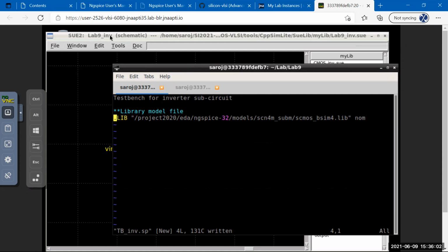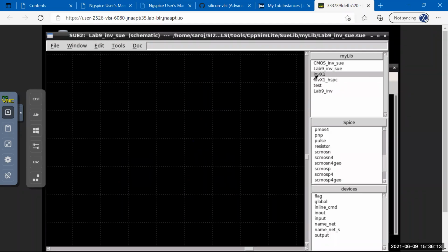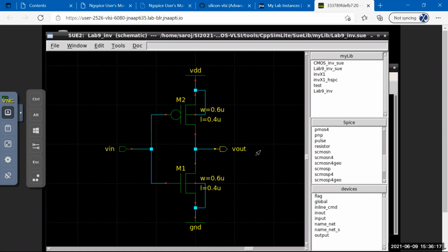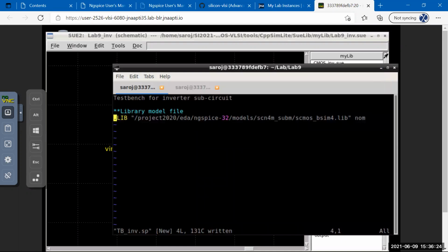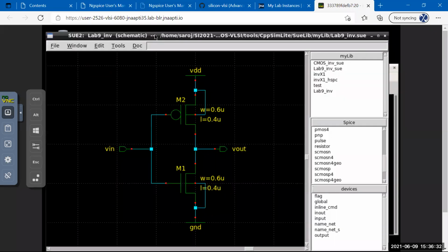Go back here and then, if you have saved it, do shift right click on the one you want to use. So for example, you want to use this, or you want to use this, or you want to use this. Okay. Just click that and then regenerate the netlist. So the .bak file you must have typed by mistake or something. While generating that netlist, it is coming empty also. What is coming empty? That netlist.